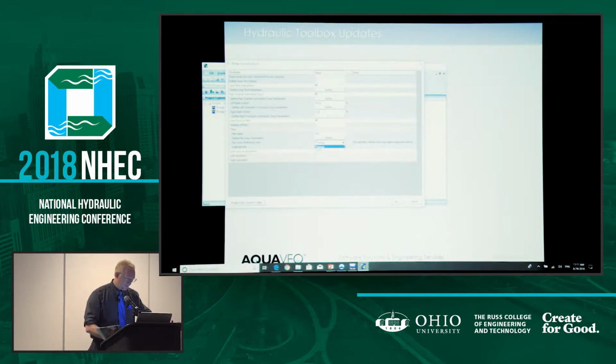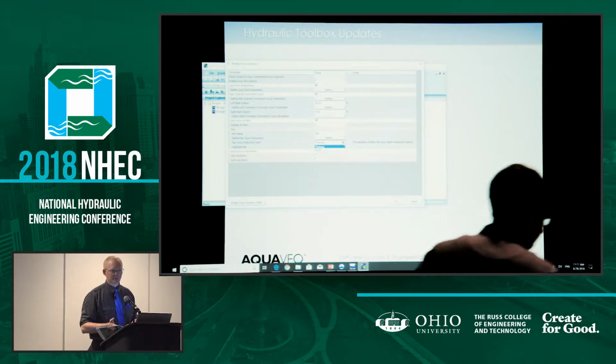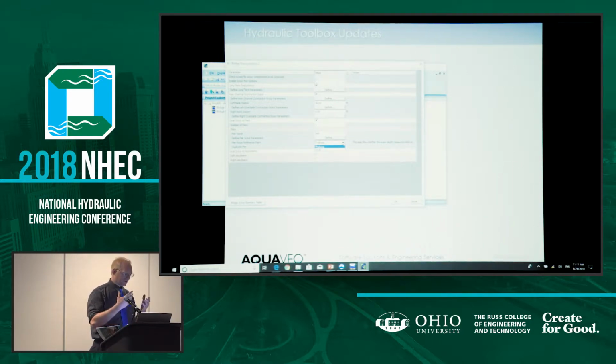And then we have the scour reference point. The point is here, that your channel and the thalweg of that channel can migrate across your piers. And so if you are determining your scour depth at the location of the stream bed at that pier, you're going to be not designing as adequately. So you can assume a thalweg, so we'll go down to the thalweg elevation and scour down from the thalweg.